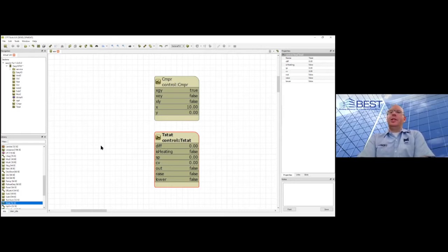But to do it exactly the way you describe, it's an external function. The way they wrote Tstat is it is script-based code. For anybody who has worked with the Niagara R2 system, the script code behind these blocks is very similar to Triple, which is the programming language that R2 used. It's kind of a hybrid between like C# and Java. And yes, that sounds absolutely horrible, but it's not that bad. It's more on the C# side.